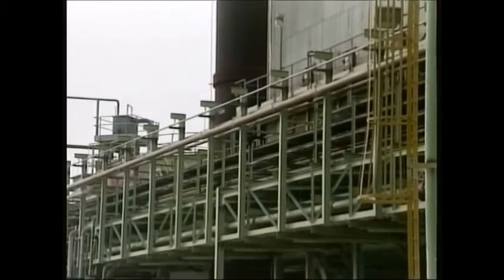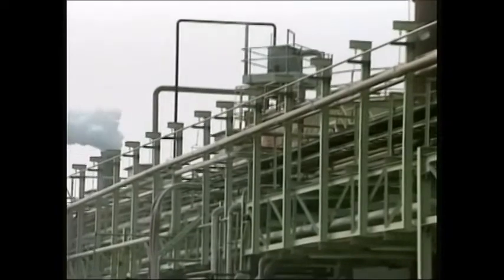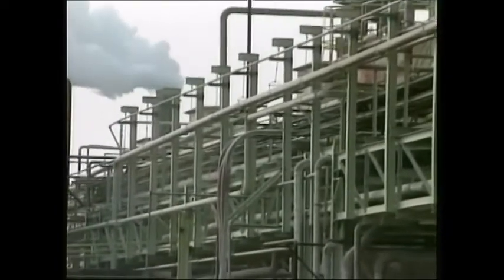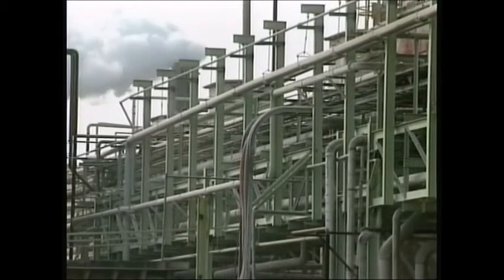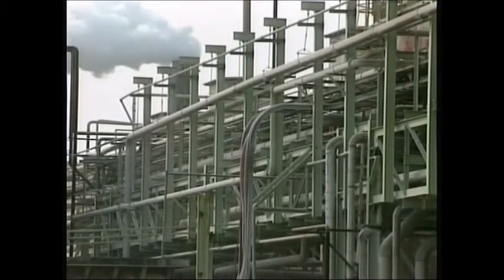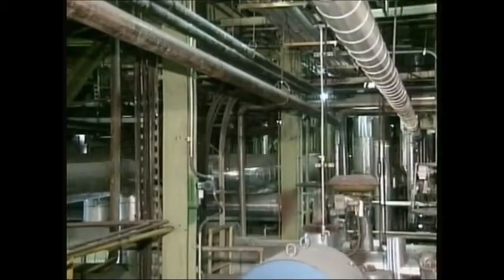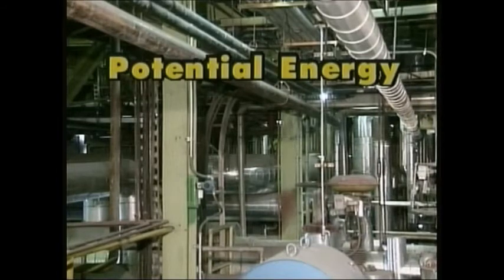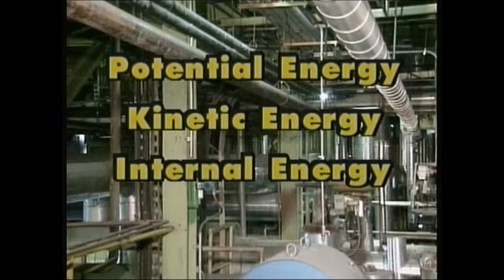In fluid process systems such as these, the reason the working fluids are able to perform work is that they contain energy, in this case heat. The energy they contain is transferred from one form to another, from one fluid to another, or from one place to another during the operation of the system. There are three categories of energy: potential energy, which is energy of position; kinetic energy, which is energy of motion; and internal energy. Internal energy is the energy of molecular motion within a substance.